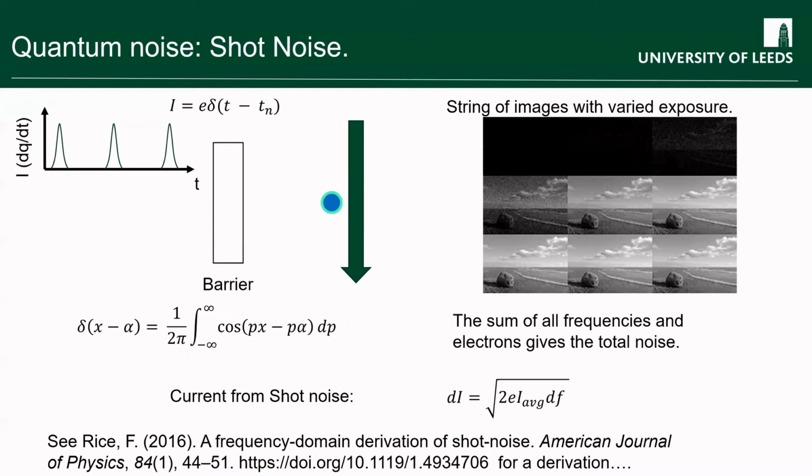So again, just like the Johnson noise appears as a square root of the bandwidth you're using for the measurement. But now it has in it the size of the individual charge carriers you're dealing with. So what you end up with is a noise that gets worse as you have a smaller signal, because the size of an individual charge carrier relative to the number of charge carriers you're trying to measure gets worse. So this is again an effect that you can pick up.